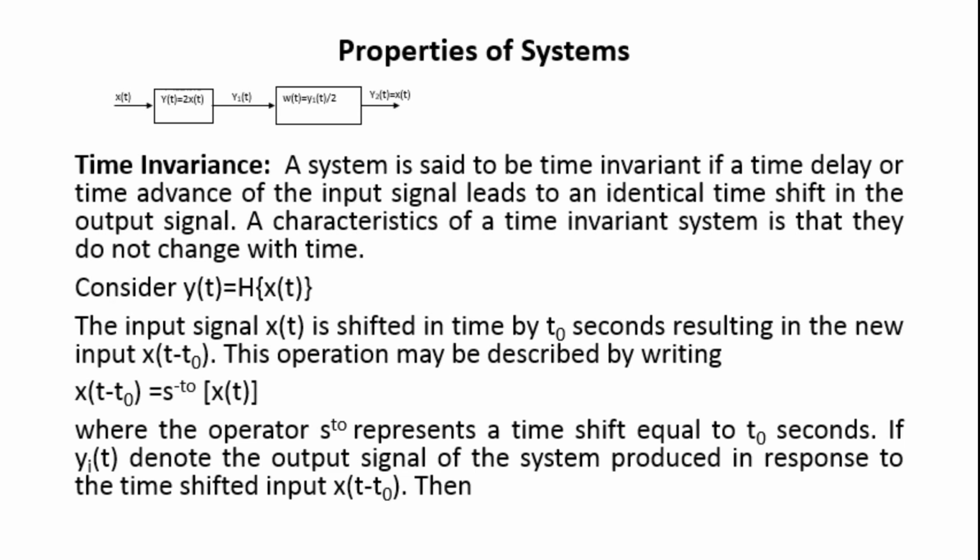Next we have time invariance. The system is said to be time invariant if a time delay or time advance of the input signal leads to an identical time shift in the output signal.